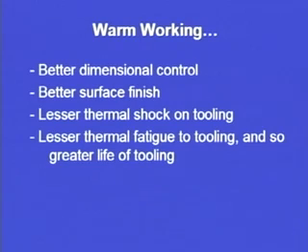Lesser thermal fatigue on tooling, and so greater life of tooling. So, the fatigue life or the life of the tooling is more as compared to hot working tools. Whatever tooling we are using for hot working, the life is considerably less as compared to the life of the tools or dies that we make use of in warm working operations.